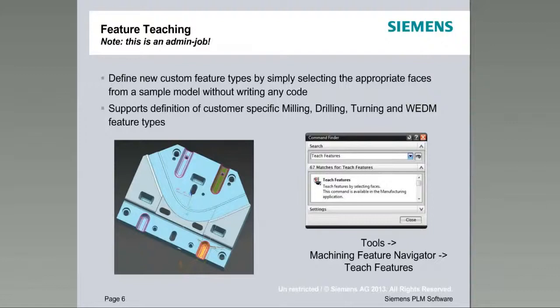Feature-based machining is extremely valuable if you can get it configured in such a way that all your users produce the same output, the same programs for similar parts. And the last thing you want to do is have each user teach his own operations and teach his own geometry. That is counterproductive. So we consider this to be an admin job, one key user from a team. You'll see me do this live today, so it doesn't require any programming skills, but it does require some careful thinking. It's an admin job that one person from a team, a key user, should be doing.